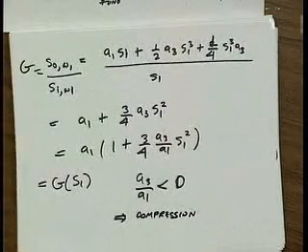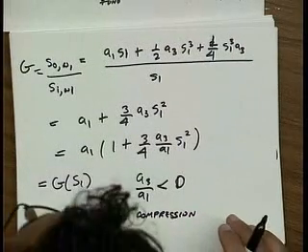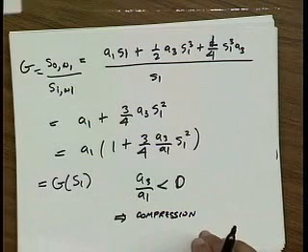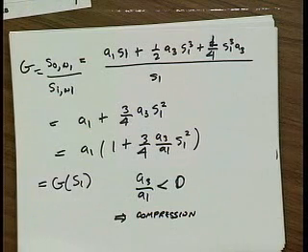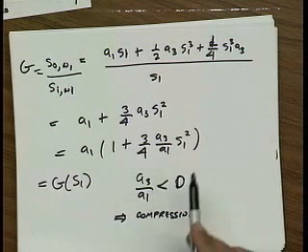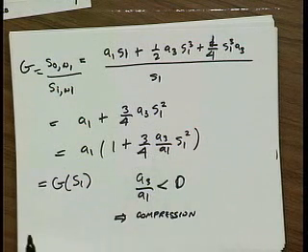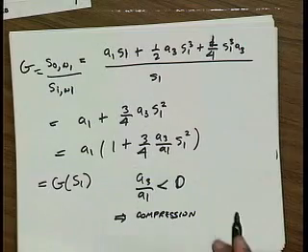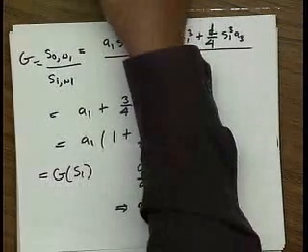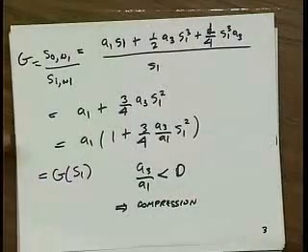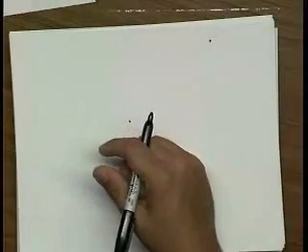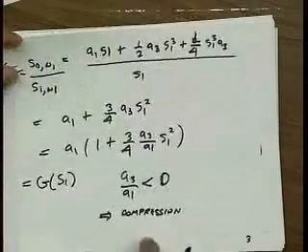Okay. Now from our general discussion, we know that any odd power will generate fundamental, right? But we're assuming here that the third order is going to dominate. That's going to be the largest term in the expansion. Any questions about that? Okay, so what we can do now is find when this gain reduces by 1 dB.